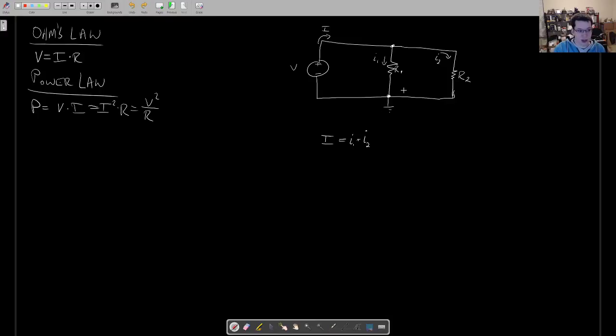If you have a very cheap meter, you'll be introducing a little bit of series resistance with each of these, which will bring it down. So these may add up to less than this guy, but not by much. Even the cheap meters will do okay. So this is something that we know to be true about the entire circuit.